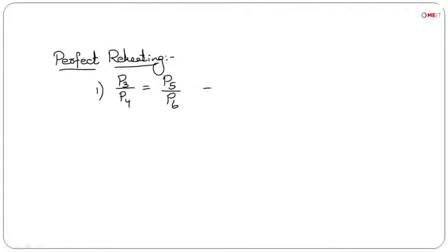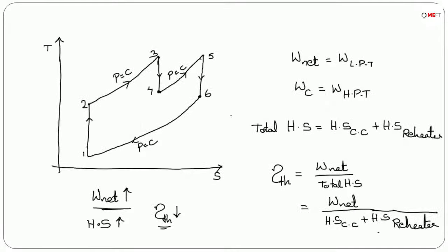So that implies the reheater pressure is remaining constant. So P4 is equal to P5. This will be under root of P3 P6 or under root of P1 P2. So why we have written like this, try to understand here carefully. P2 is equal to P3 and P6 is equal to P1. The intermediate pressure or the reheater pressure is P4 equal to P5.